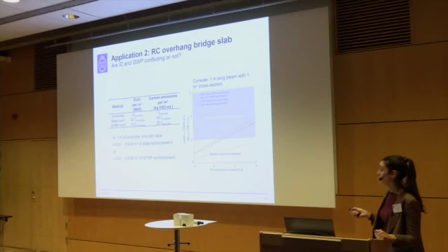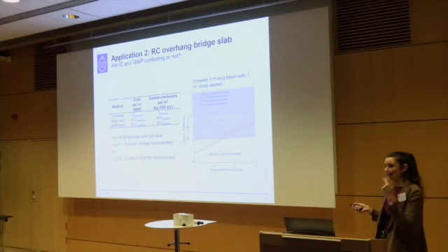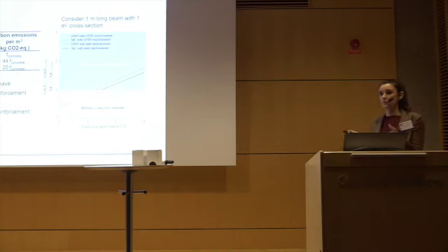It seems like the reinforcement is always the bad guy. But then we remember, it's reinforced concrete. So in 1 cubic meter of concrete, we have a super tiny amount of reinforcement. We have between 1 and 4% for steel, and 1 and 3.5% for GFRP.